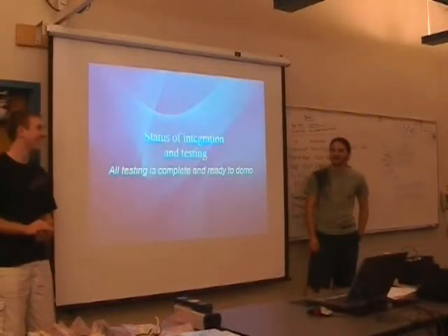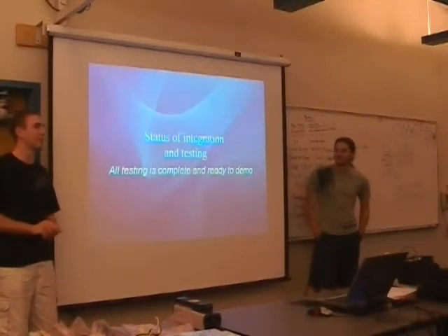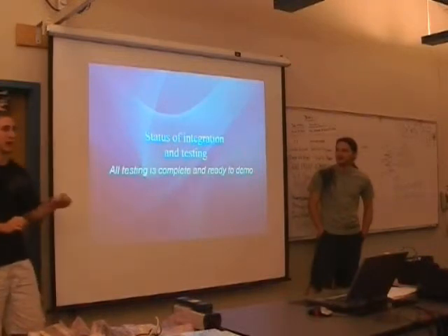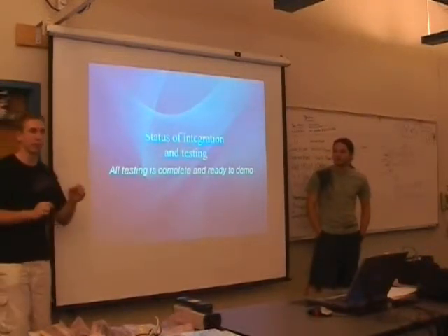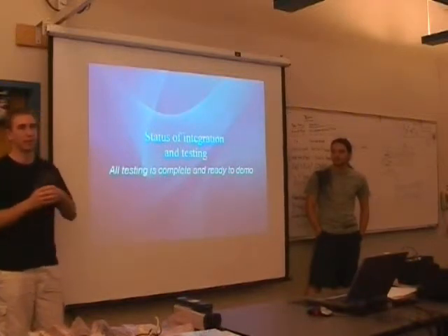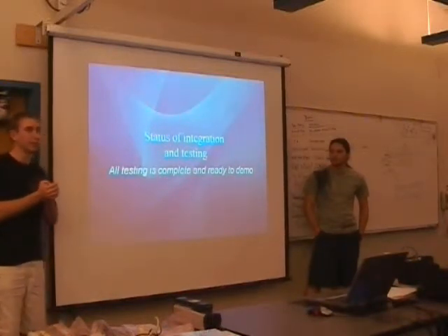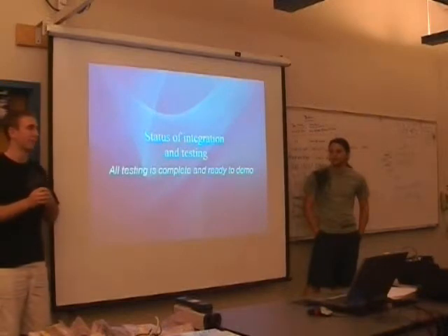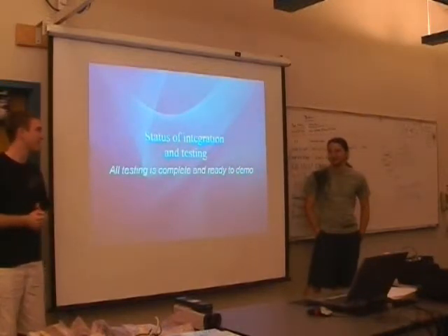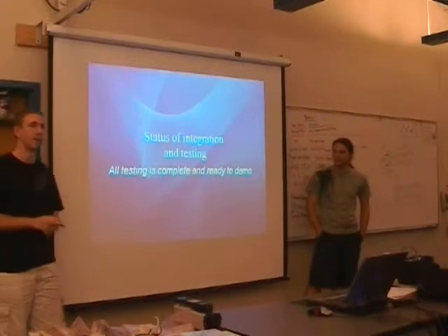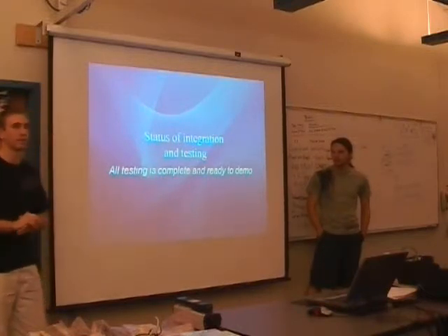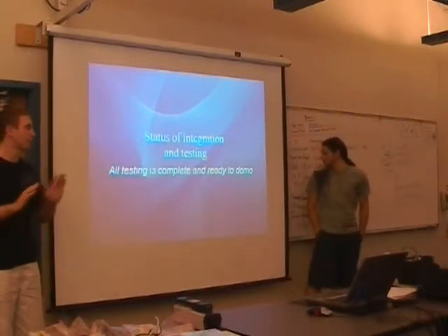Also the voltages were a bit different. We were able to drive the single LED with the Nexys board, but RGB LEDs are 20 milliamps per color, so that's 60 milliamps per LED, and there's just no way the Nexys board was able to power all that. It's 16 per bar times 2 bars. It's a lot of current, and that's where we ran into problems. After we had all the external circuitry, that was fine, and then we went to the task of trying to get VGA with it and just sort of mirror it.